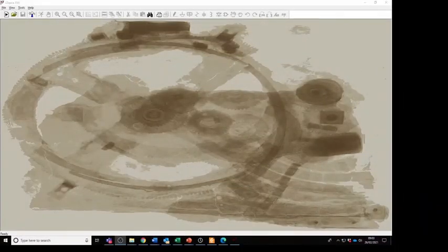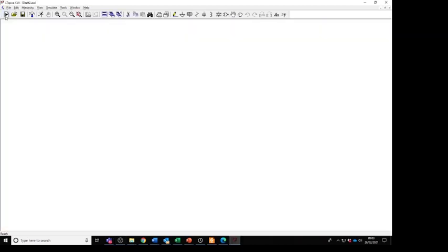So this is LTSpice. This is the screen that you'll get up when you open LTSpice. Hopefully the first time, if it all works properly. What we need to do to start with is open up a new schematic. So let's just click on there. So now we've got a new schematic, and that means that we can actually start to put components and things on this blank piece of paper, really.